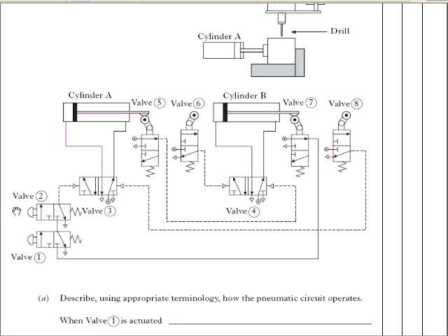So valve 2 has then got to be pressed before pilot air gets round to valve 3, and this half of the piston will slide over, so connecting that port to there. So cylinder A will go positive, activating valve 6, which activates valve 4, making cylinder B go positive. So cylinder B has now gone positive. Now that activates valve 3 to make this happen here, so that is going there. That makes cylinder A go negative.